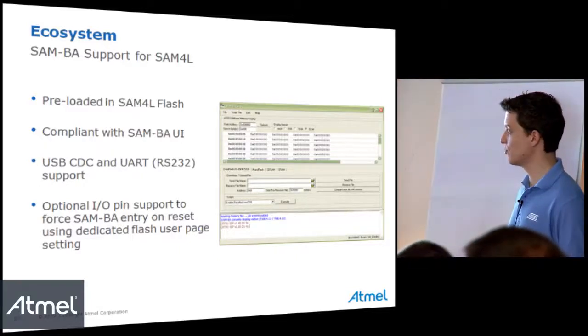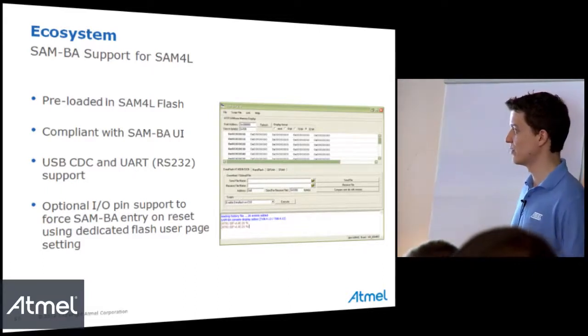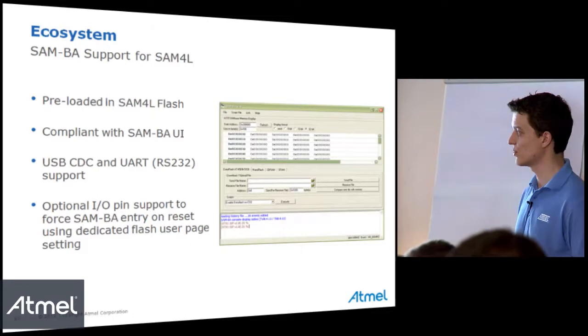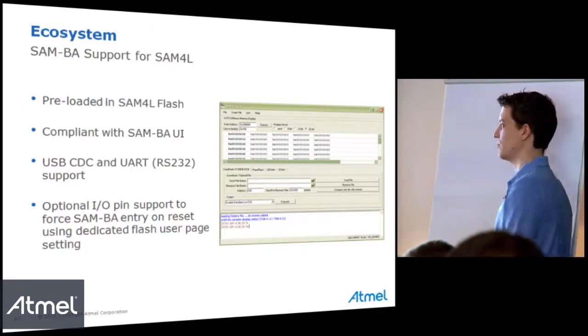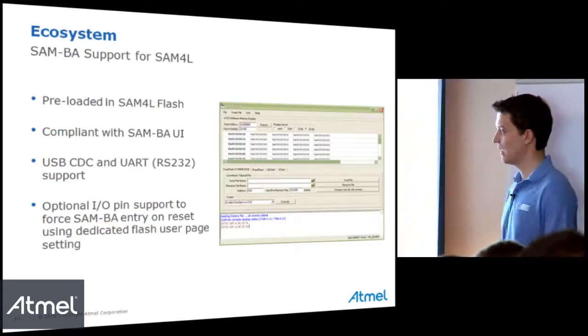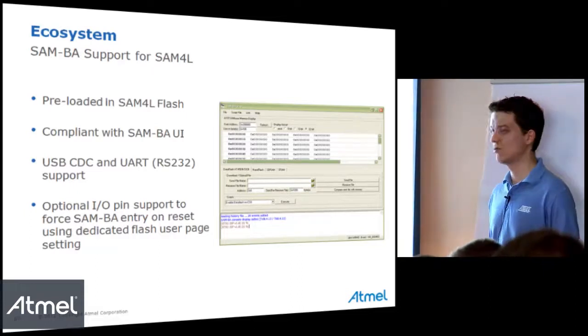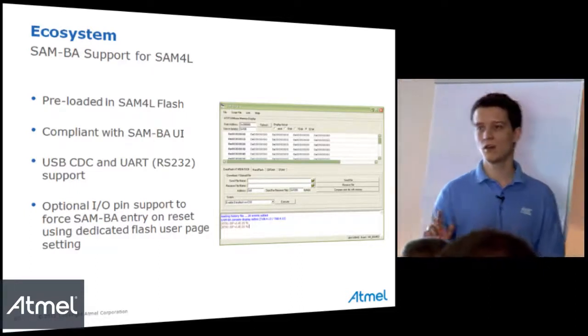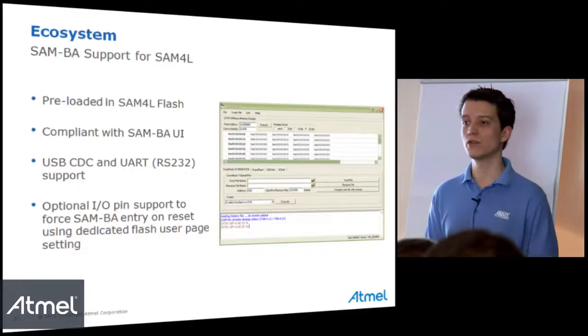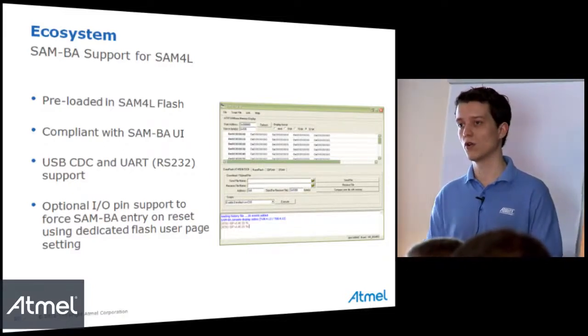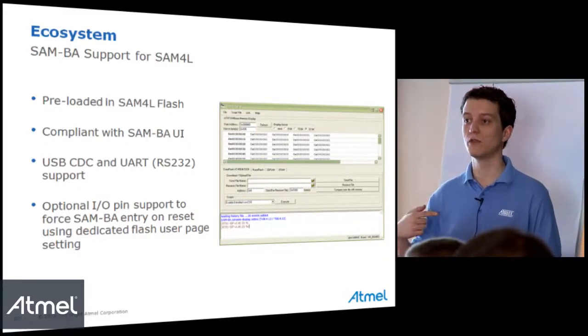It's compliant with the SAM-BA user interface and has the same functionality as the standard SAM-BA, so you can communicate with USB or UART. In addition to the standard SAM-BA, you have the possibility to set some IOs in order to enter or not into the SAM-BA boot method.